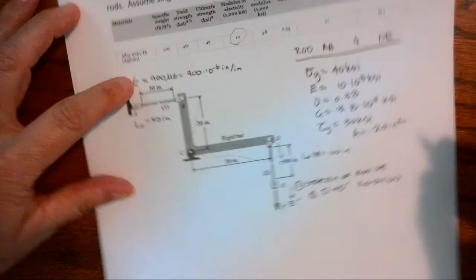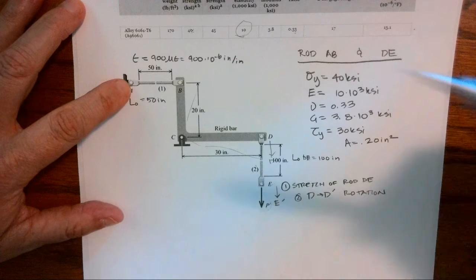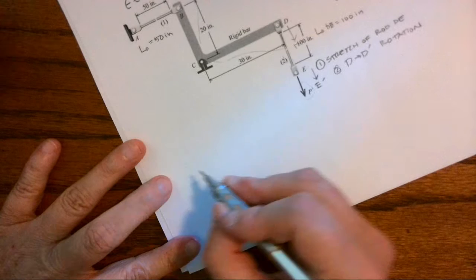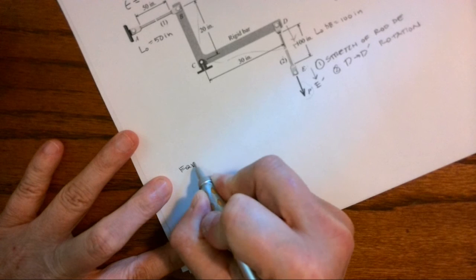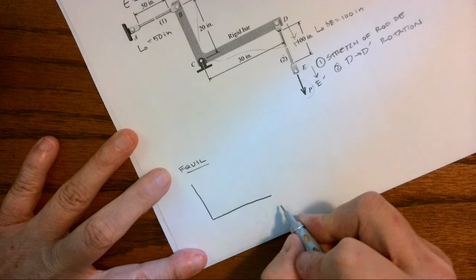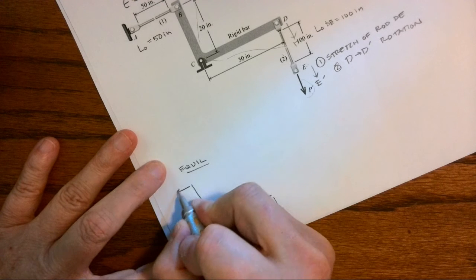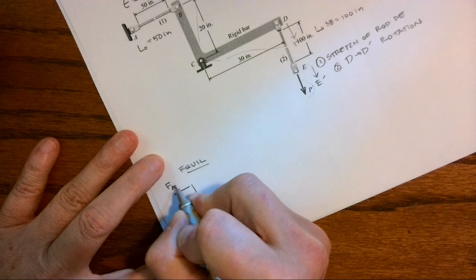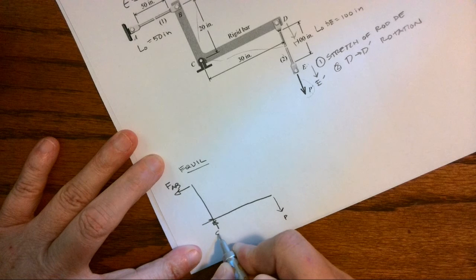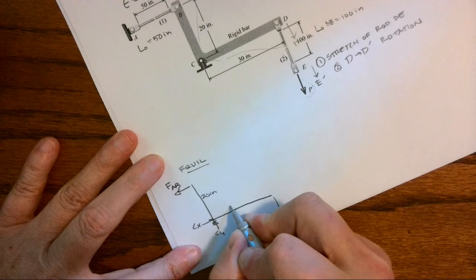So far, the only thing we know that's different about our loaded system is the strain that happens in this cable. So before I get started, I like to just go ahead and draw out my free body diagram. So if I'm looking at equilibrium, this is what we would see from statics. I have a load P, which is acting through that cable. I have tension, which is the force in AB, and I have a pin here. So I have CY and CX. This is 20 inches tall, 30 inches to the side.